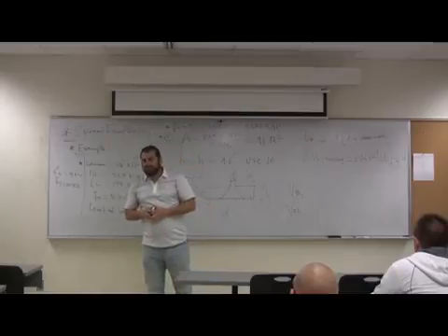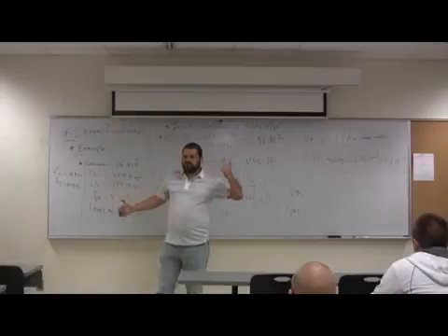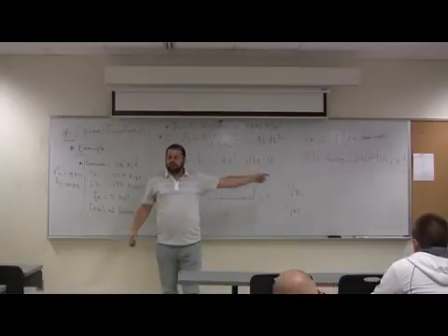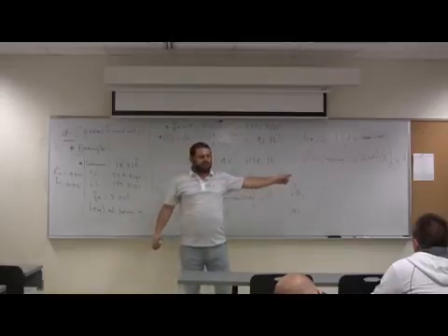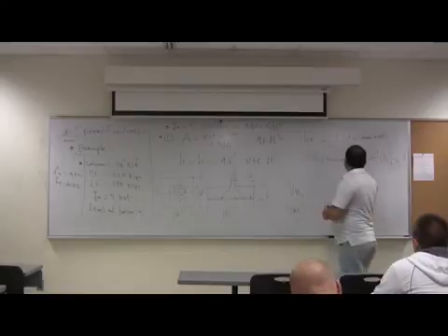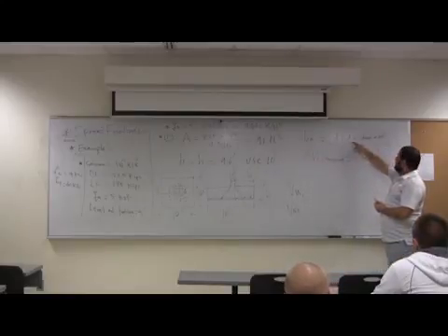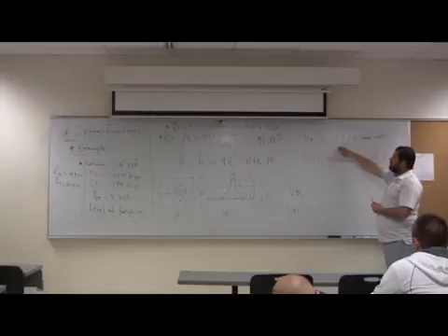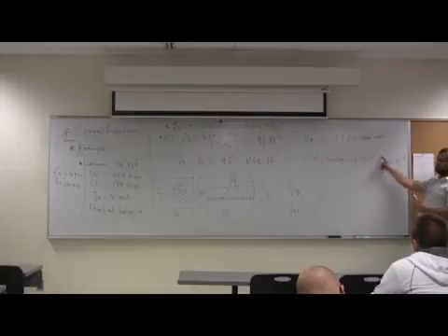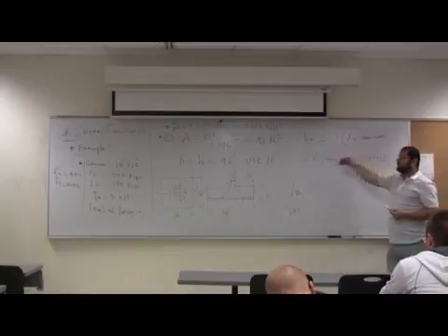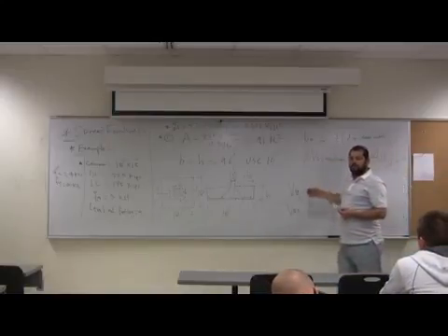So we're going to assume d. Try h equal 24 if you want to check this one. d will be 19.5. If you want to be conservative, take 19.5. Once you have 19.5, that's your d. Here, 19.5 plus 18 times 4, that's b naught. 19.5 plus that times 4 gives you this one in inch. Then 175 times 4 times square root of 4,000 times that, divided by 1,000 to get it in kips. Okay? Now what's Vu2?